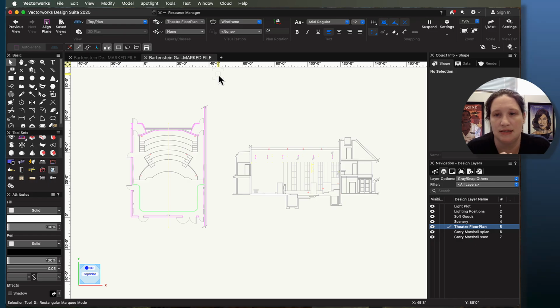The next step that I'm going to take, the format that I'm aiming for, is sort of an important piece of this equation, okay? I want my ultimate drafting file to have an origin that is the same as the origin of my drawing. This is important because it makes it easy for us to snap different people's drawings together.